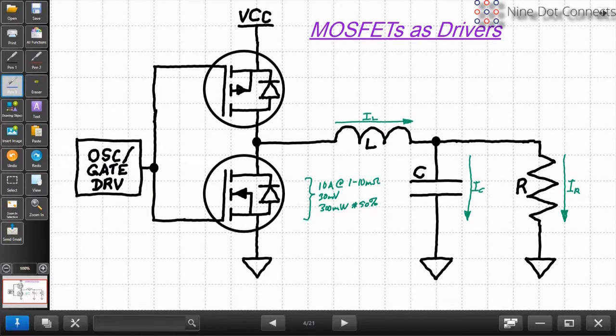Note that the voltage on a gate, if you read many specs, can typically go both positive and negative with respect to the source. So it can be like plus or minus 20 volts, a large voltage. You need to go up to, say, 5 volts above the source to be able to turn on. But you can reverse bias it a lot. It usually is fine. And you can also take it far up over the voltage where you can't do that with a BJT. In a BJT, the base emitter junction turns on and starts conducting a lot of current.